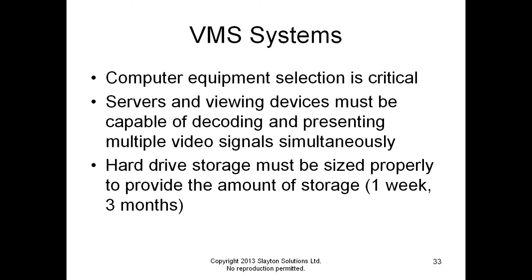Now, when you are looking at video management systems, the equipment you use is critical, and what's critical about it is you can't watch, let's say, 16 or 20 cameras simultaneously on a $400 or $500 PC. It won't work. That PC does not have enough processing power to process all those video signals at once. So the guy's not going to be able to see them.